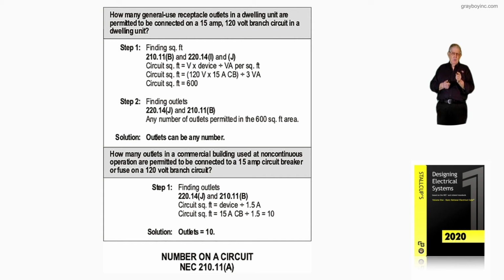But in a dwelling unit, if the state, county, or city do not limit the number of outlets, you can go in and add outlets for lights and other loads in that square footage area. How many rooms fall within this 600 square foot? That's what the electrician's supposed to know. Unfortunately, we have so many electricians that just don't know this, and they should apply themselves better.